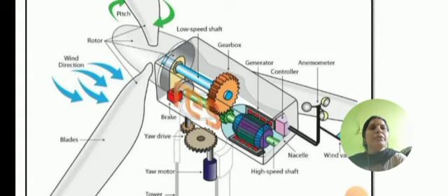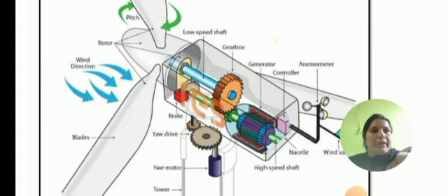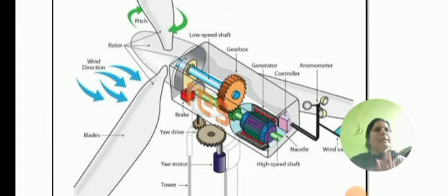And next we are going to focus on the control unit. The main purpose of the control unit is to limit the power exerted at high wind speeds, that is, above the rated speed, and to start the turbine below that speed. High speeds typically happen only for a short time. However, if they are not controlled, they will damage the drivetrain, gearbox as well as the generator.